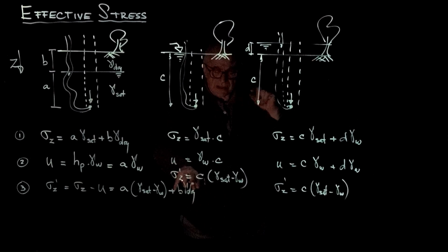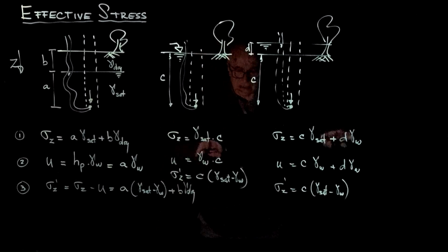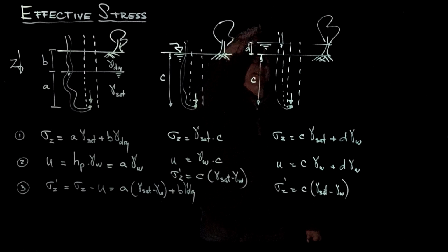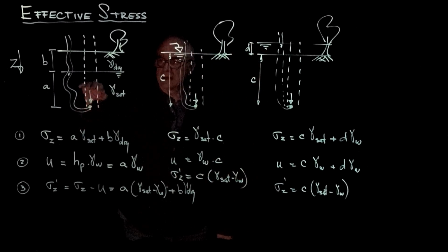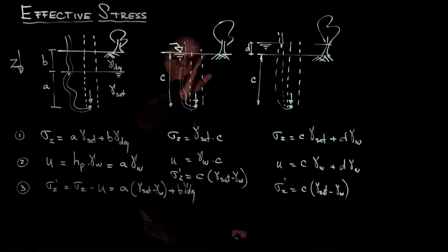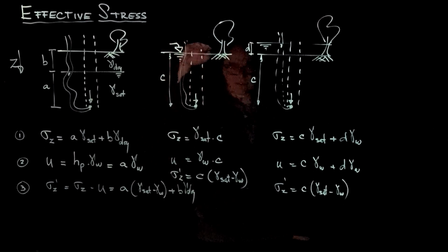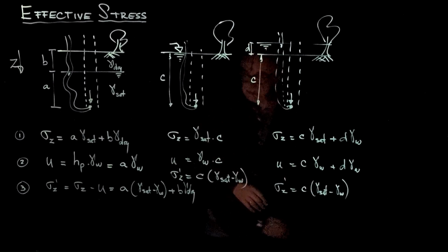So whether it is 1 centimeter above the sediment or 5 kilometers above the sediment, the near surface will have exactly the same effective stress, because the pore pressure due to the excess water above the seafloor cancels out. So to summarize, as the water table increases, the sediment is decreasing its effective stress. Once the water is above the surface during a flooding event or on the seafloor, then there is no more difference. The effective stress remains constant.